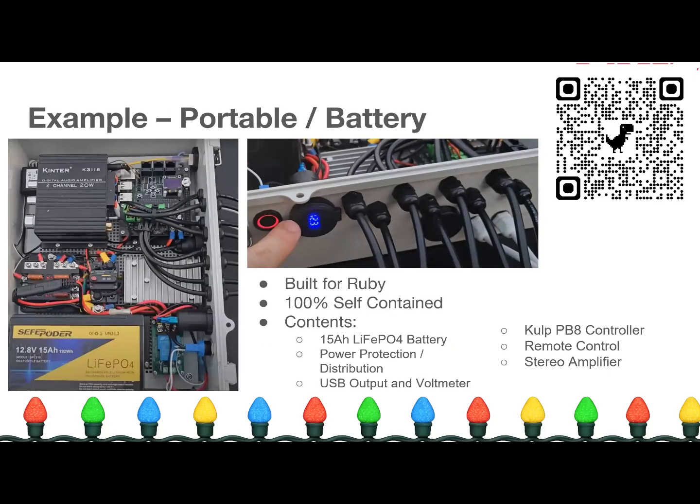So this is an example of that box I was talking about that I built for Sherry Cone. Here at the bottom, we've got a lithium polymer battery. This battery goes to the circuit breaker, and then the circuit breaker goes to the buck boost converter. So this regulates to 12 volts. With Sherry's setup, we're using 12 volts, and this just makes sure that we stay at 12 volts. So even if the battery voltage dips due to the battery draining, we'll still regulate up to 12 volts until we no longer have sufficient power.